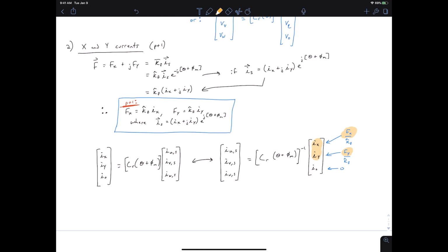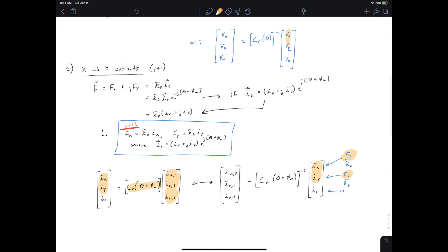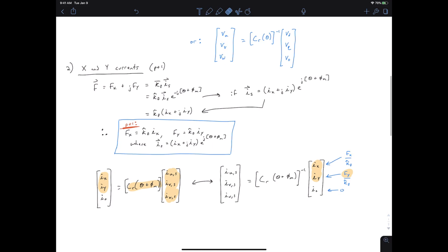So that is, we're going to take our measured suspension currents, do our dq transformation to get out our Fx and Fy force-producing currents, or x and y force-producing currents. We're then going to feed that into a current regulator in this frame and generate dq or xy voltage references that will transform back to the UVW domain.